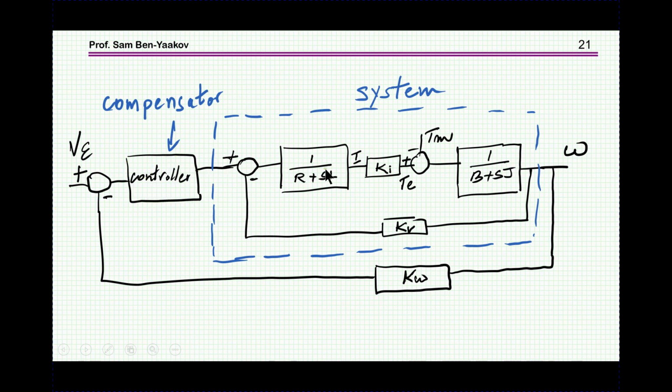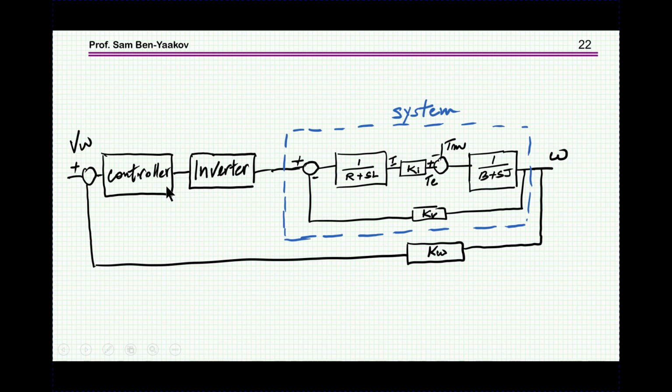And then we have now a closed loop system in which we have one part here and this one part here. This is a beta, and this is sort of the new open loop with this controller. And our task now is to come up with a controller that will ensure stability and also the bandwidth that we want. That is the response time that we want.